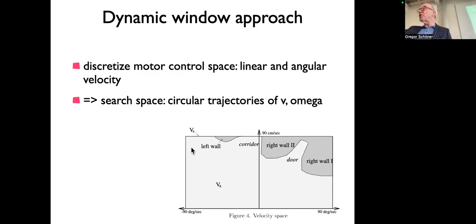And then you use this configuration space approach idea, that is, you translate any distance sensing you have, like here from the walls and so on, ultimately into a polygon in the space. And the idea is that you do that by computing the boundary you define here: the speeds at which you could still stop before you hit that obstacle. So you have a distance measure in certain directions, right?